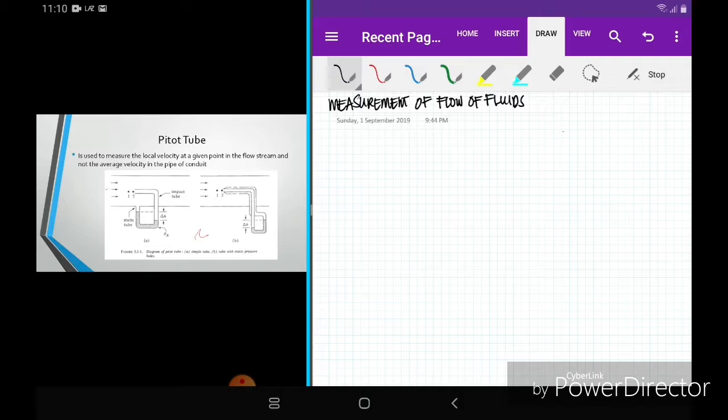The most simple are those that measure directly the volume of flowing fluids, such as ordinary gas and water meters and positive displacement pumps. Current meters make use of an element such as a propeller or cups on a rotating arm, which rotates at a speed determined by the velocity of the fluid passing through it.